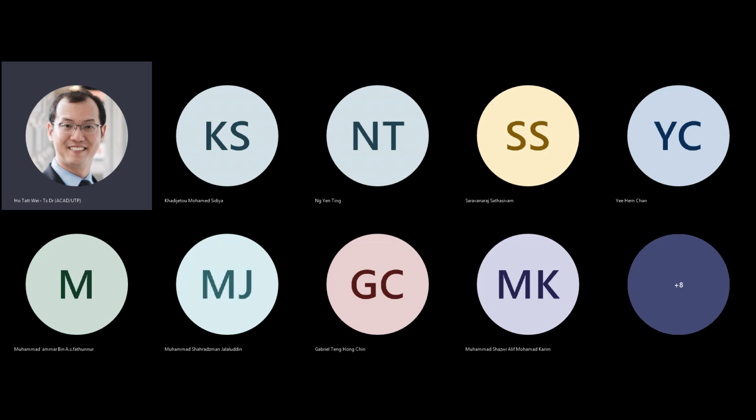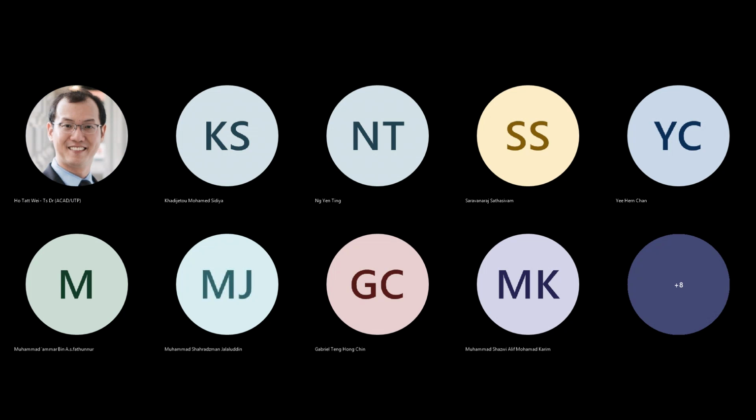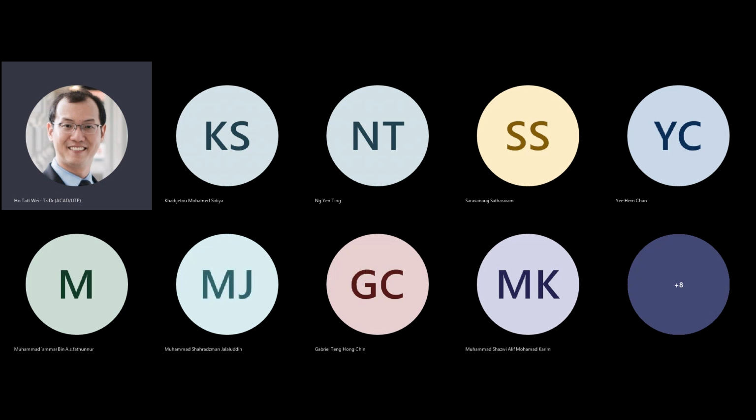So if the delays are TPD1, TPD2, TPD3, TPD4, the clock duration is actually set by the maximum of TPD1, TPD2, TPD3, TPD4.